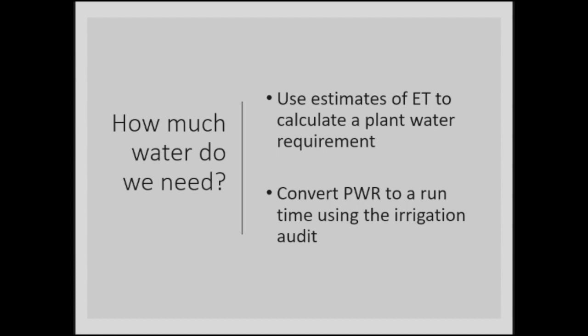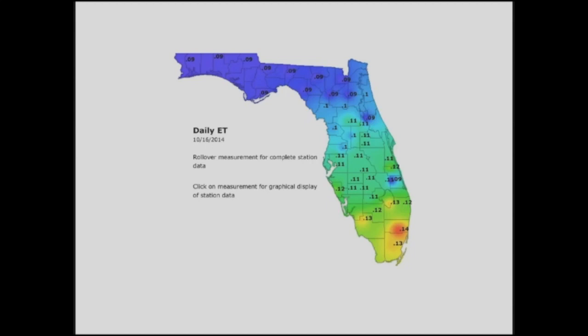Okay, so there's a lot of systems out there that will tell you the daily ET. The typical one, what's the typical in the South, kind of in Texas? Typical number that you would hear in Dallas, for a home lawn, is water 1 inch per week, right? That number comes from the average ET lost that week being 1 inch.